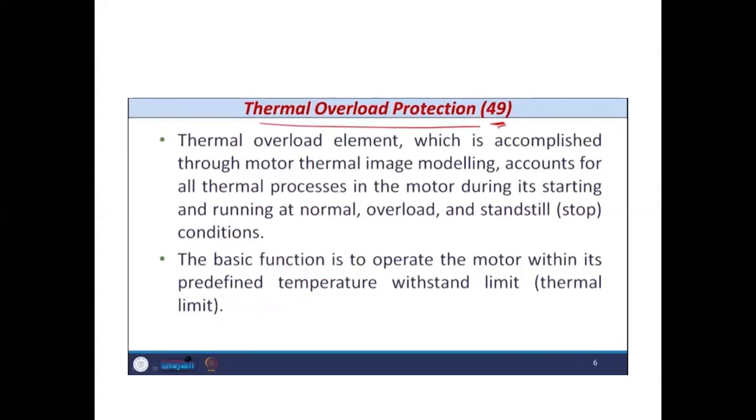So the thermal overload element is accomplished by modeling, or image modeling, of the motor, and that is accountable for all thermal processes in the induction motor.